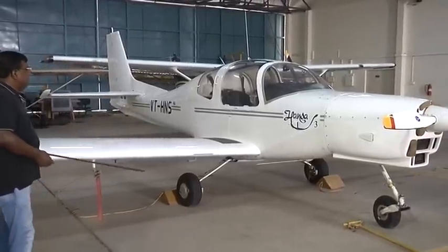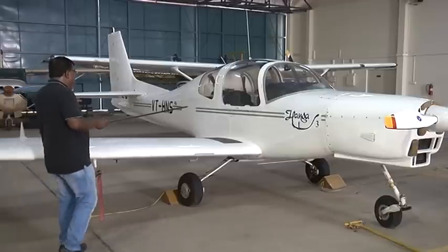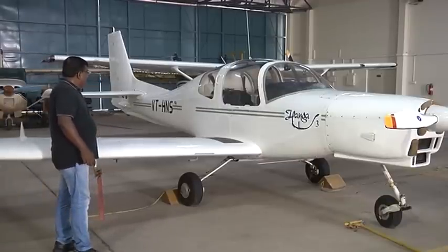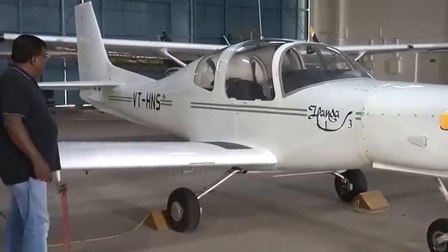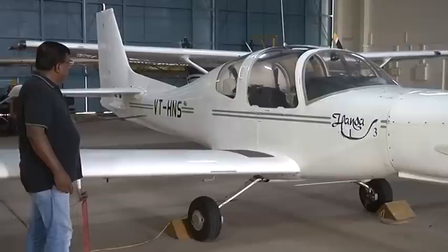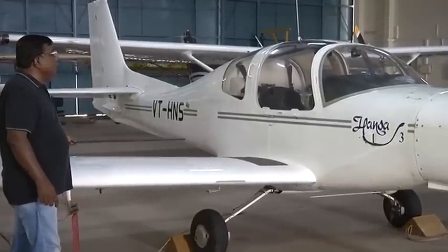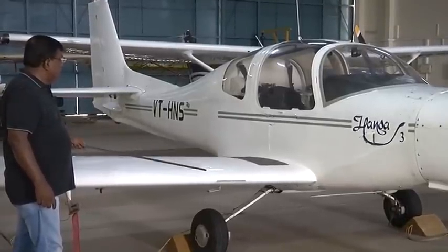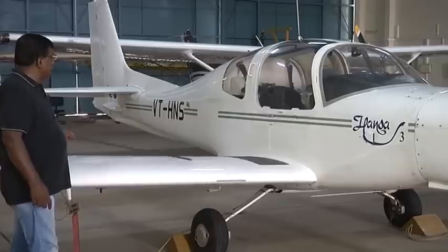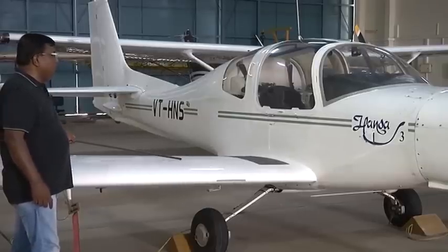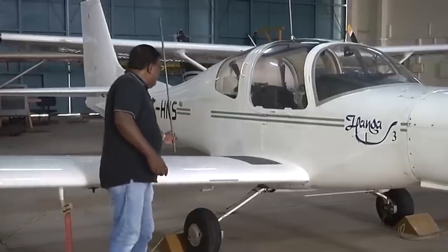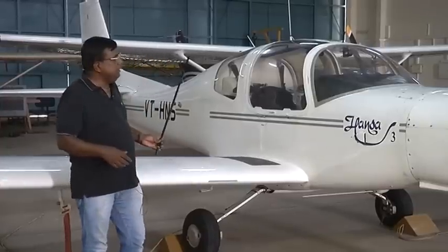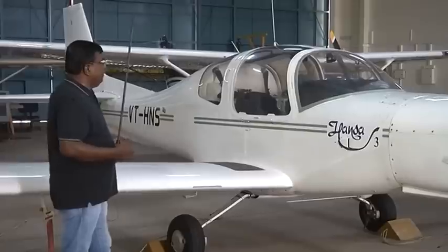Right? Before I stop discussion on this, please also understand we have also shown you that over the wing, if I try to represent where the lift or CL will act, I know that it should be at the quarter chord point. That is, I take this chord and act 25% from the leading edge. So I'll say this is my CL, location is here. Okay? So these are the things which need to be kept in mind.